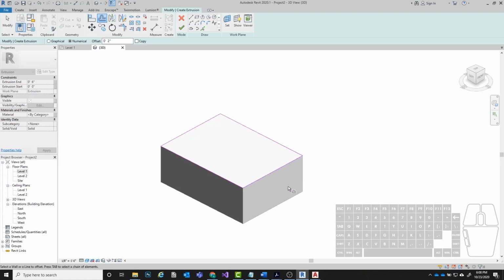Hover over one of these. Make sure that your preview line is facing inward. Then press the Tab key. That's going to cycle through another option you have, and it's going to do all of the lines at the same time. It basically chains them together. And now if I click once with my mouse, you can see it does them all at the same time. Okay?